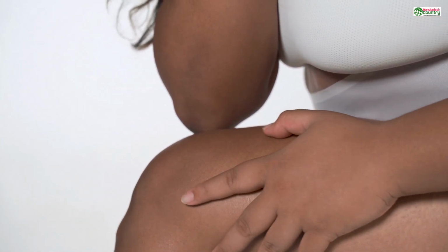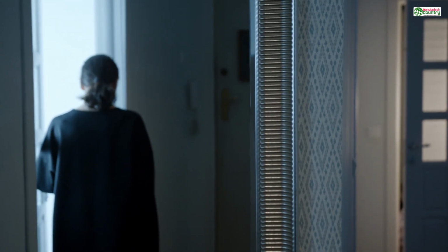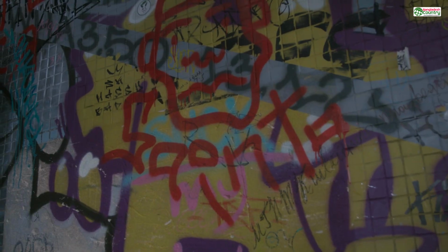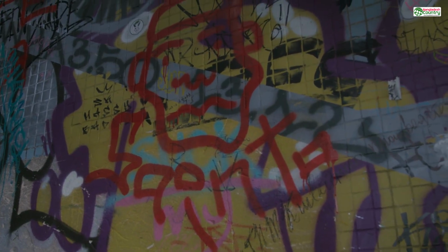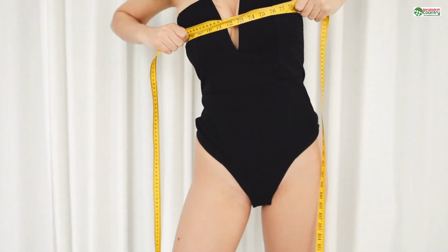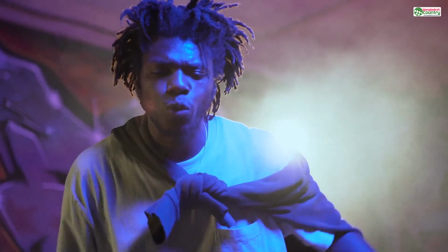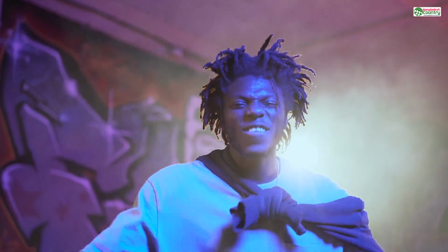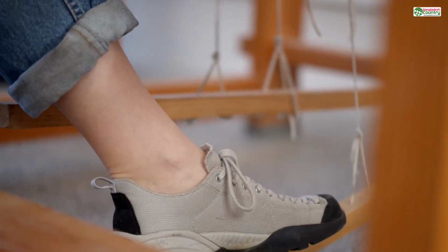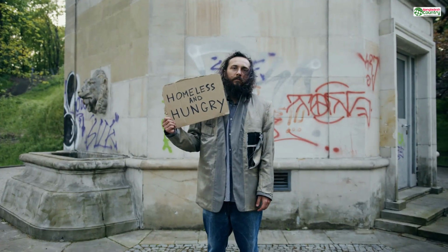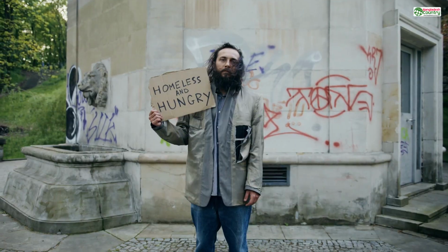The right wall thickness depends entirely on two things: the size of your model and the material you're printing with. A small 2-inch figurine made from a strong nylon might only need a wall thickness of 1 mm. But a large foot-tall sculpture made from a more brittle resin might need a 3 or even 4 mm wall to support its own weight without warping. Again, the cheat code here is the design guide from your printing service.